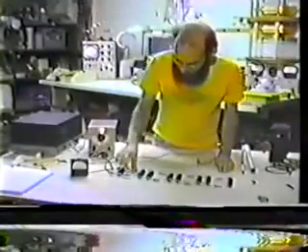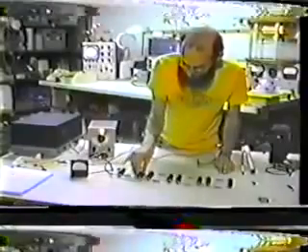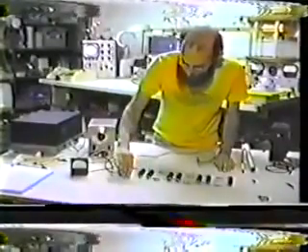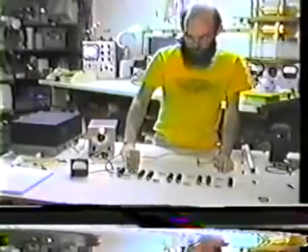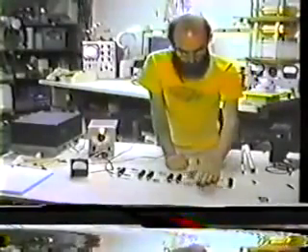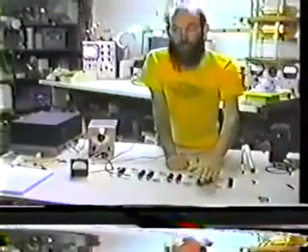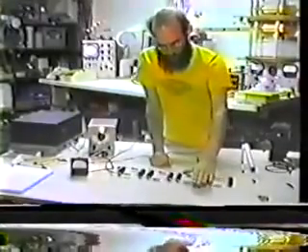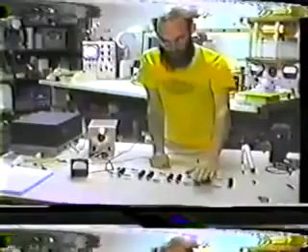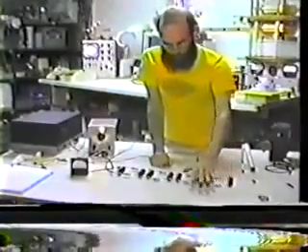And we'll do our heat check again, see where the heat's coming from in here. Feel our input coils, relatively cool. The input capacitors are quite hot. Go down the line here, capacitors are cooling off, but the coils are very, very warm here, this end. So now we have the situation where the heating effect is turned around from where it was before. Now the dielectric input capacitors get hot, and the magnetic output inductors are getting warm. So we have quite a few differences here.